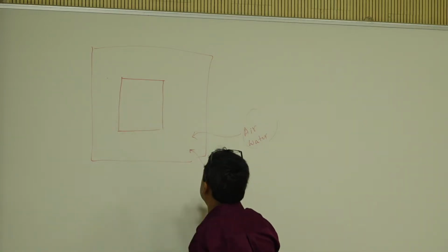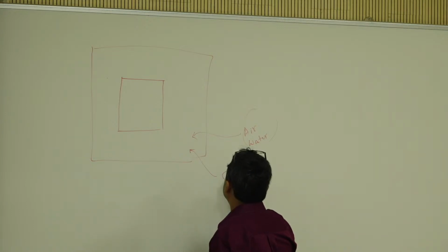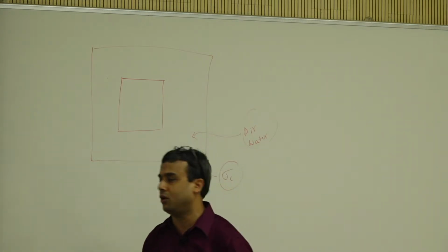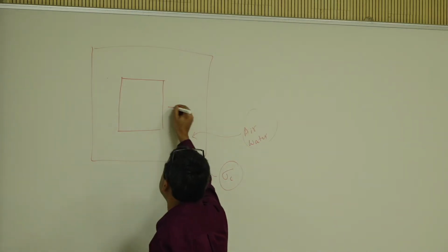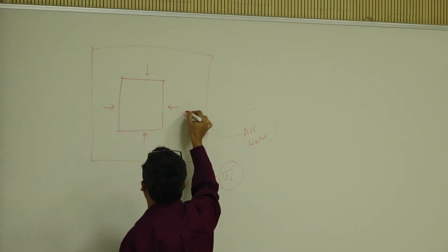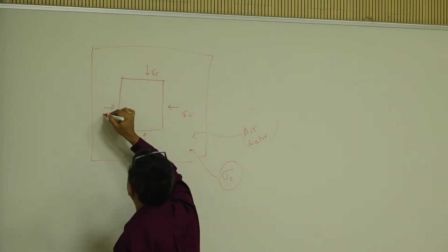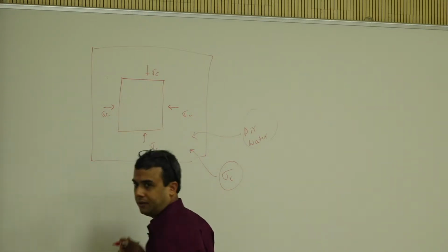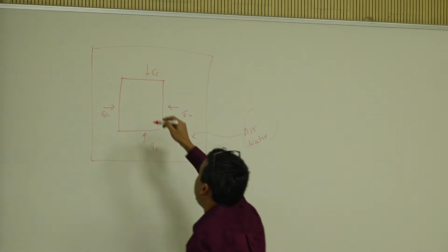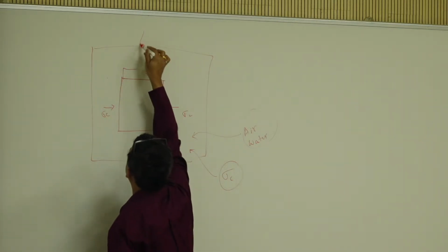So what happens is, sigma c is the confining pressure that you apply. So at the very initial stages, you have all of these as sigma c, right? And then you have a mechanically applied deviator stress.